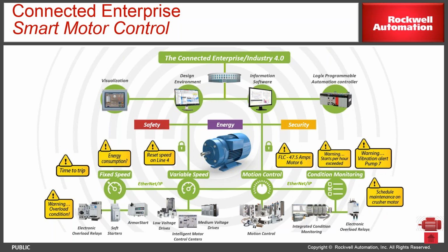Now, the most important innovation of being IoT connected is that we not only get the status, whether it is on or off, but also the condition of the device, the motor and the thing that it is driving. So for example, the amount of energy that has been put into the motor over time, which if trended, will give us the condition of the device we are driving. Maybe it is increasing the load because the oil is not getting into the machine. So along with the integrated condition monitoring, we can monitor the mechanical health of the machine and predict things that will result in the stoppage or damage.